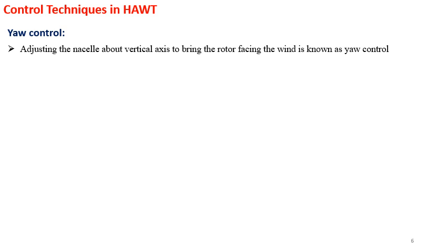For localities with the prevailing wind in one direction, the design of a turbine can be greatly simplified. The rotor can be in a fixed orientation with the swept area perpendicular to the predominant wind direction. Such a machine is said to be yaw fixed, that is, it cannot be rotated around a vertical axis perpendicular to the wind stream.